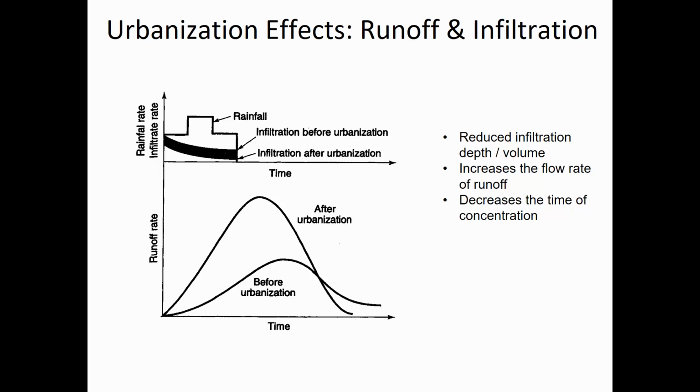So the runoff hydrograph is the peak is sooner and higher. This figure is showing two things. The hydrograph, which I've just shown you, and above that, this is called a hyetograph, a rainfall hyetograph. And so the hyetograph, this one, is breaking the rainfall up into distinct periods. Rather than measuring it continuously, they're reporting an average during a certain period.